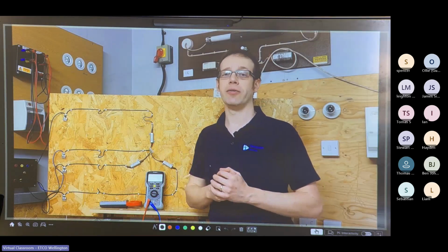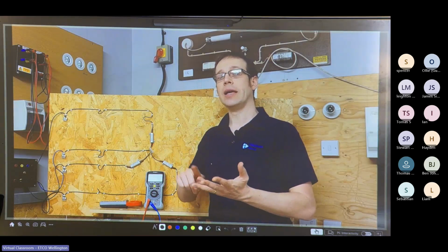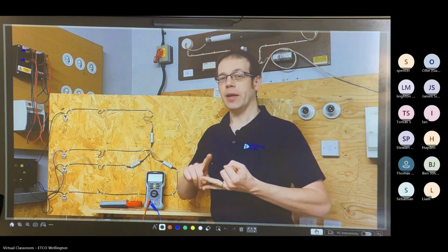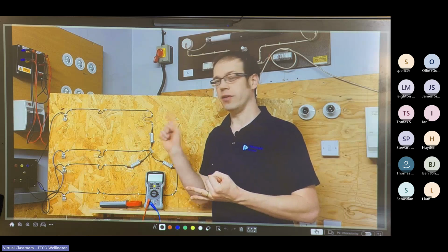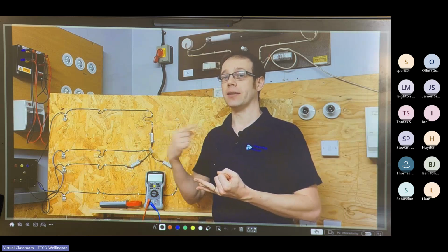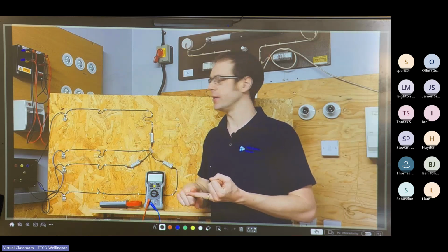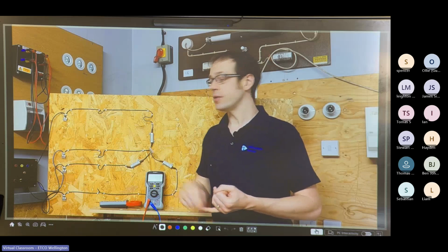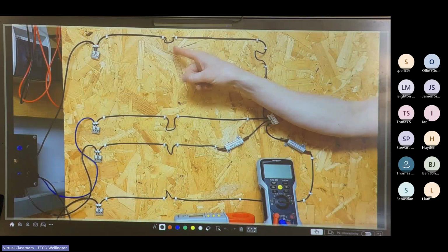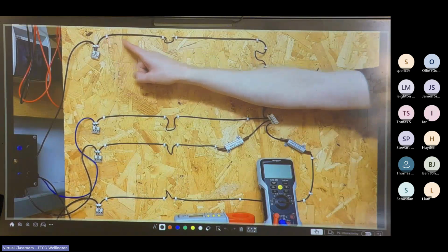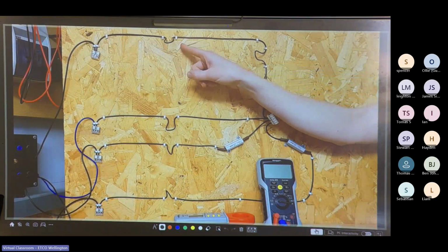So then we've got our 2 different kinds of current. We've got line current and we've got phase current. Now, at first glance, the definitions that I'm about to give here might seem pretty absurd for a star-connected load. You can see that they're going to be really useful when we get to the delta-connected load. So the line current is the current flowing through the supply line to the load.